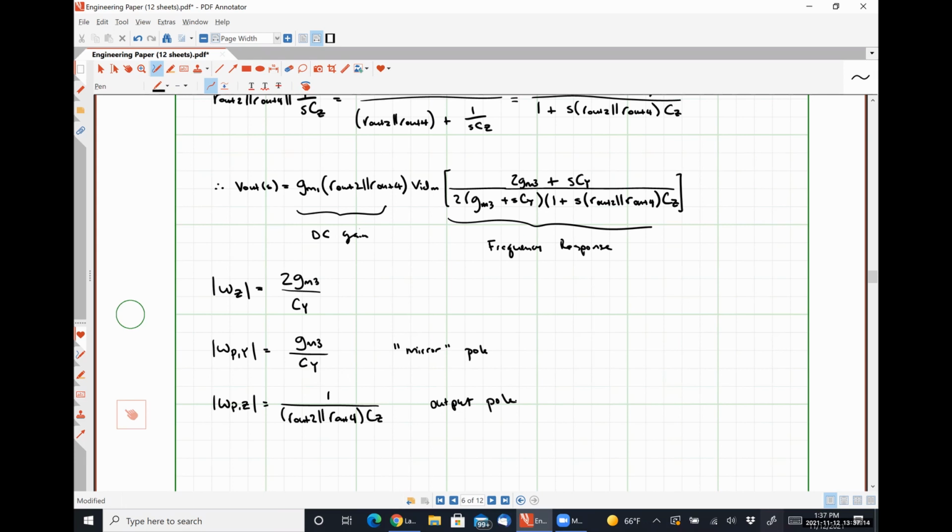and a zero. And so what can happen, and we'll talk about this in depth on Monday, is that because we have a 2-pole system, we can see that if our gain doesn't fall to 0 dB before we hit a 180-degree phase shift in our signal, we have an unstable system. So effectively, this guy will work for low frequencies, but for high frequencies, our output is just the hottest of garbage. And so we have to learn how to compensate that.